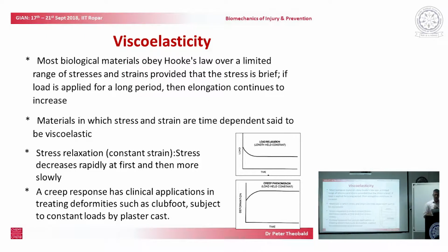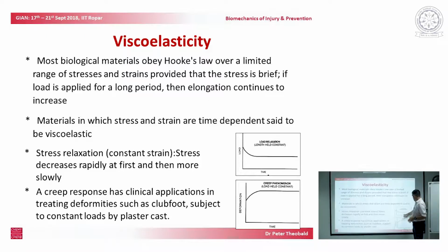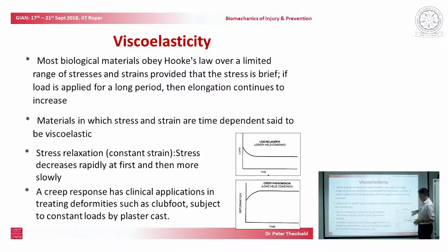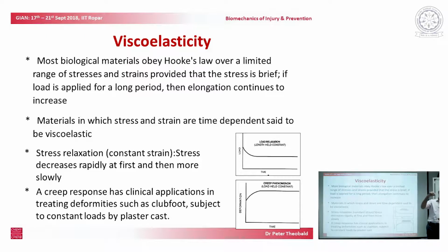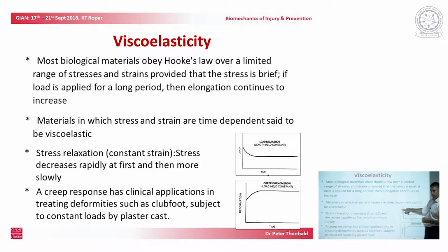Tendons are yet another material that have viscoelastic traits, and that is that if you hold the tendon at a fixed length in a machine, so you would load it to a certain length, you would walk away from the machine, and you would come back, and the reading on the machine, the load on the machine, would be lower. If you had a piece of rope and put it in the machine, walked away, came back in 10 minutes' time, you would be confident that the machine load would remain unchanged. So the load cell wouldn't have in any way had a reduction in load exposed to it.